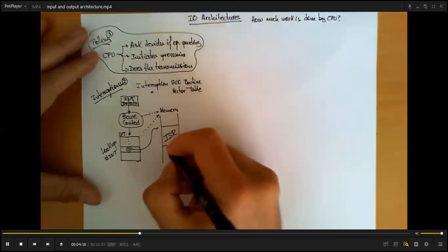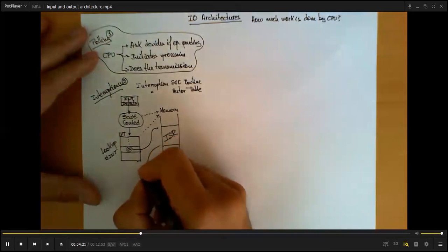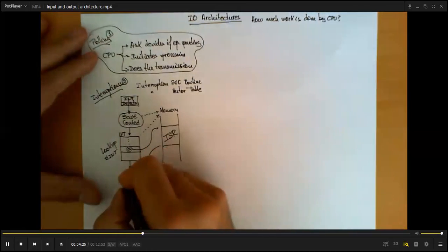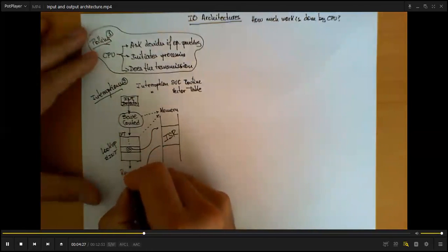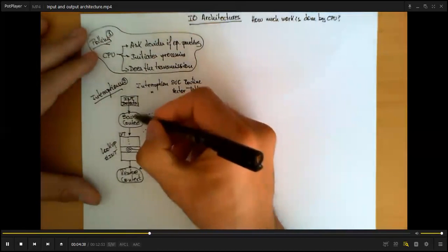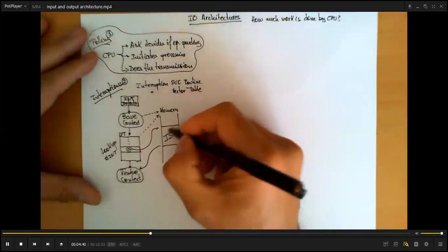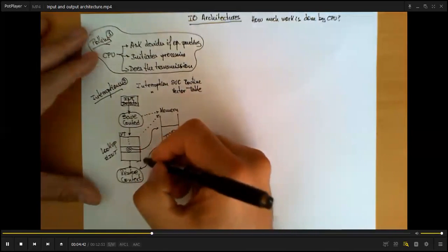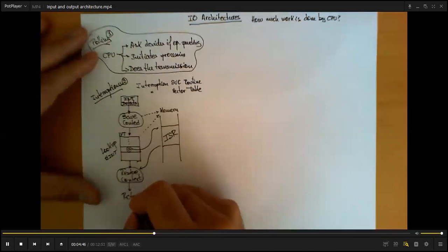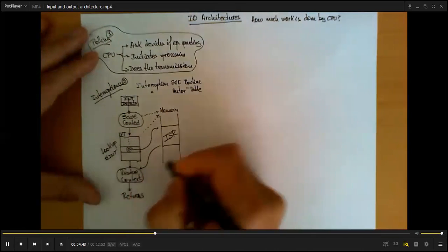After this interruption service routine has been executed, then we have to return to the way the CPU was working before, which means first we have to restore the previously saved context. In other words, we leave the CPU exactly as we found it in this place over here, as if this interruption service routine had not been executed. It's not going to leave any trace on the context of execution, and then the microprocessor returns to the regular execution.